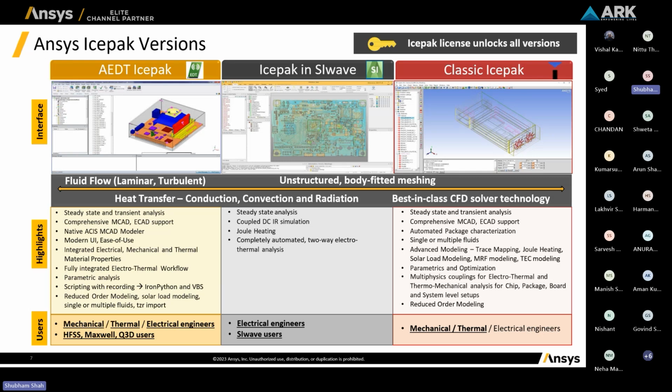Let's say you are also using cooling channels to cool down your electronic components. There are multiple ways we can simulate or analyze the thermal behavior. And once we know our system is heated up pretty high, we then design the cooling jackets. We design the thermal path for cooling. In that case, there might be multiple fluids involved, so that will come under multi-phase flows. Multi-phase flows is also supported in Icepak Classic.